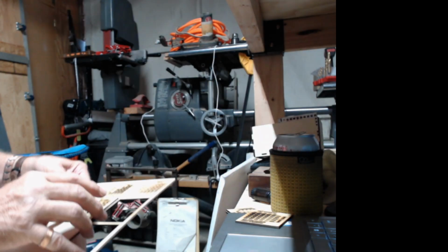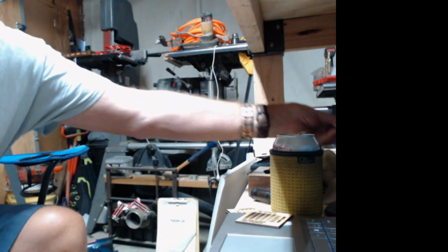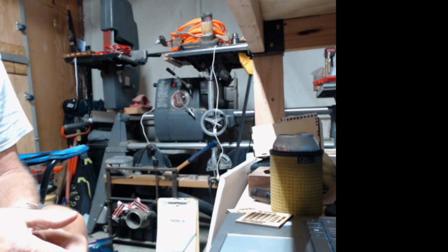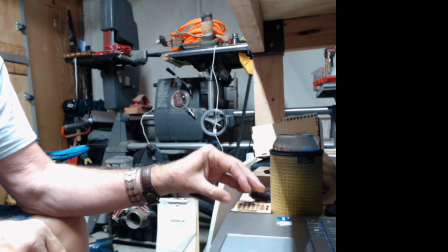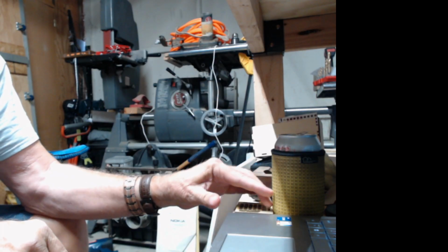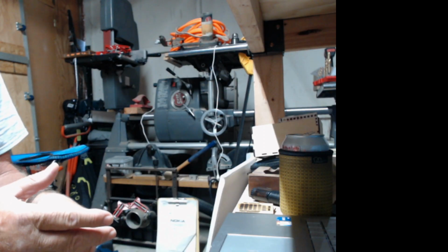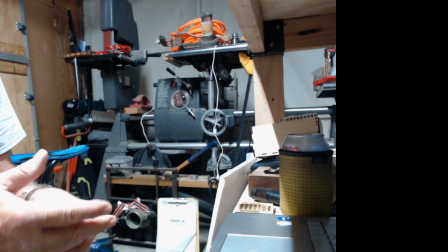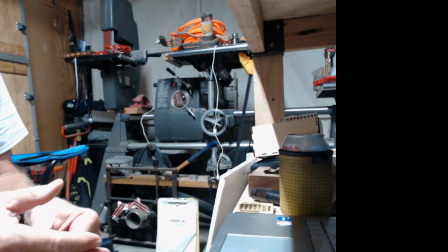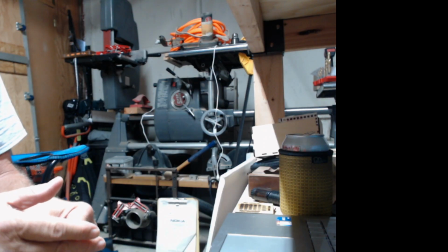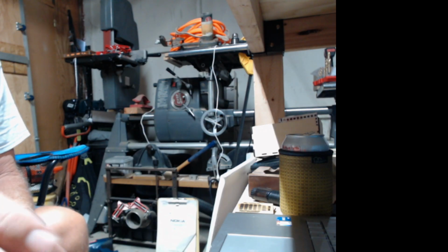All set there. So that's basically how you do a speed and power test for your laser. I showed you both versions so that you could do it on any software that you have. I think that xTool probably has these kinds of settings already set up in it, like LightBurn has, where it has the default settings and you just change those settings to how many you want. You don't have to manually enter every single square. Like I said, I'm not really familiar with it. I haven't really used xTool.